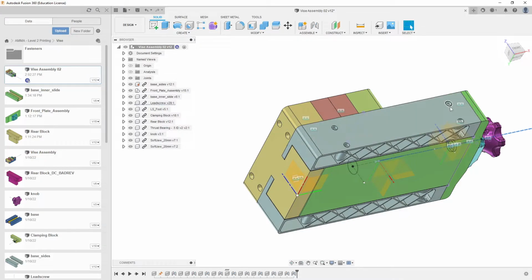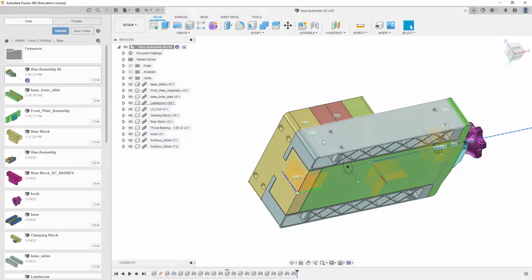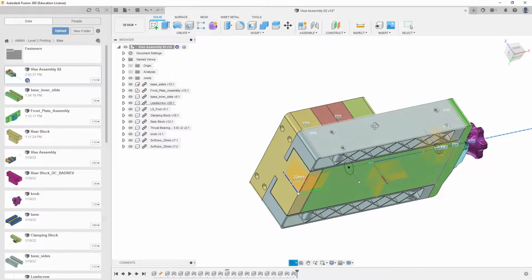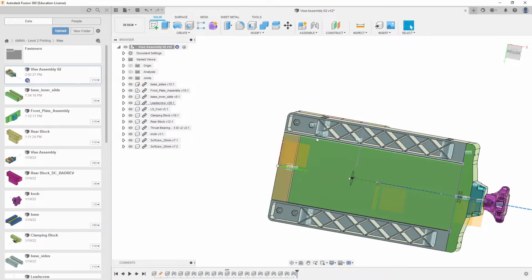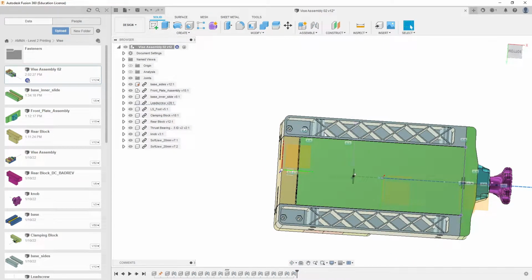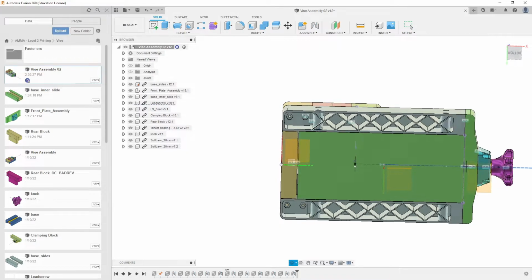We have a handful of things. This is one side right here. This is another side right here. These two sides are screwed into the front, and then they screw into the sides over here, which should not be an issue. It should be okay. But due to the way that you print it, upside down, sideways, whatever, if you have any warpage, these holes might not quite line up. Now, it has not been my experience that that's happening too badly, so maybe that's a smaller issue.